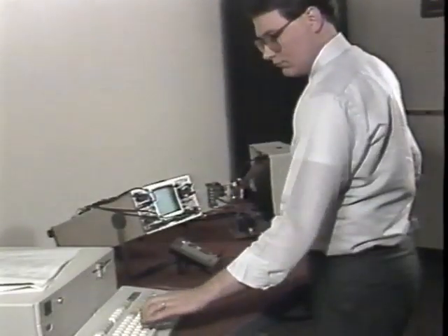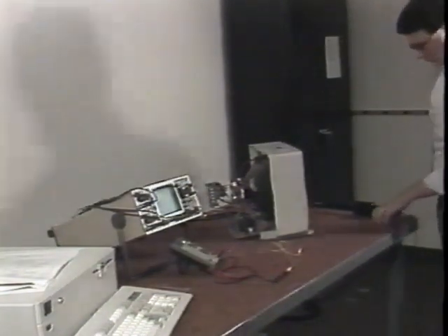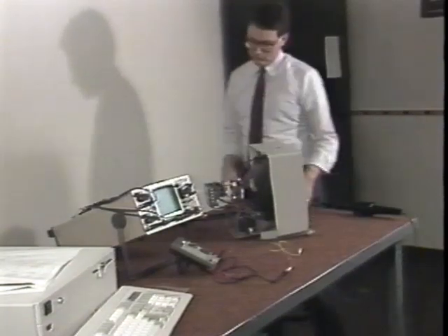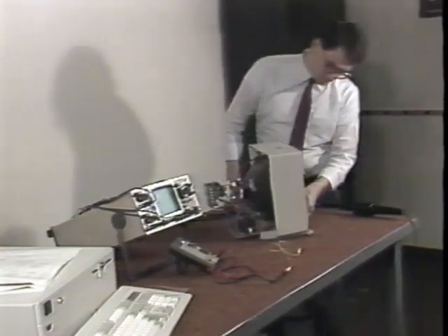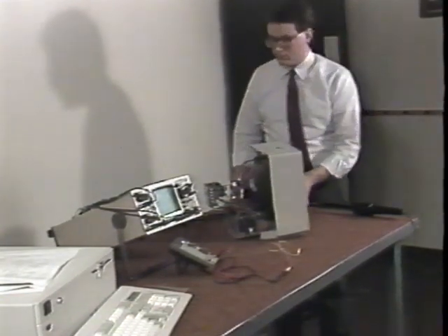To begin this adjustment, select the dots option from your video alignment program. This will produce several small dots scattered about the screen. Turn the intensity control down until the screen is dim but still readable to reduce the effects of varying beam drive on the adjustment.